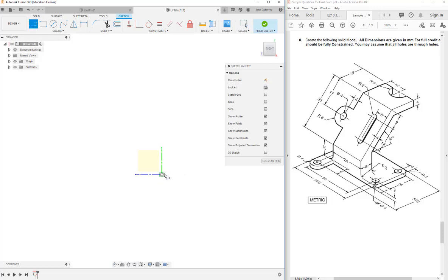I'm just going to go ahead and use the line tool, and what I'd like to do actually, as I've shown this, as I've created the sketch, is open up the sketch folder. That way I can look at my sketch and watch it to make sure I've fully constrained it, make sure I get that lock feature on there.